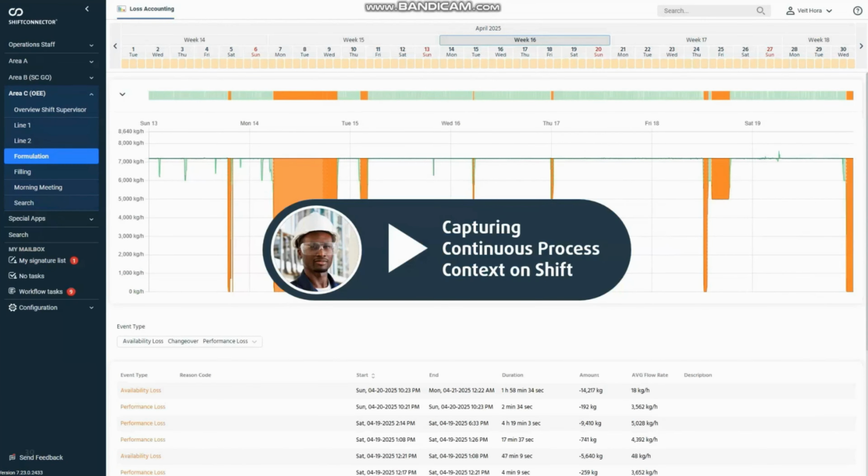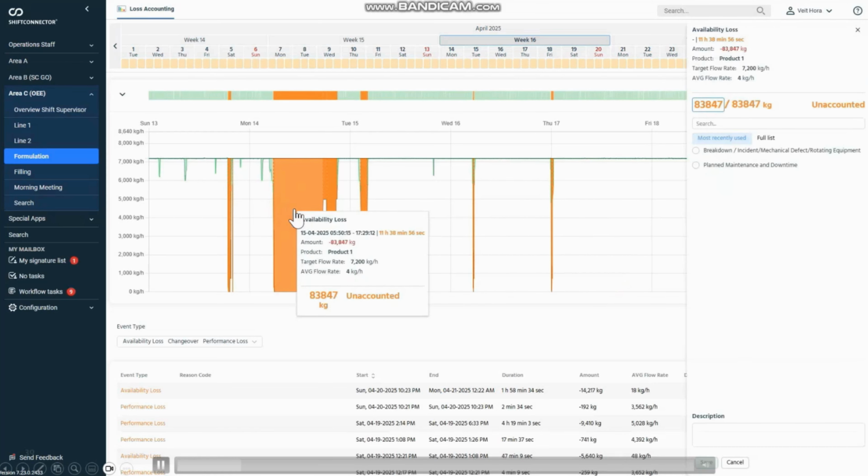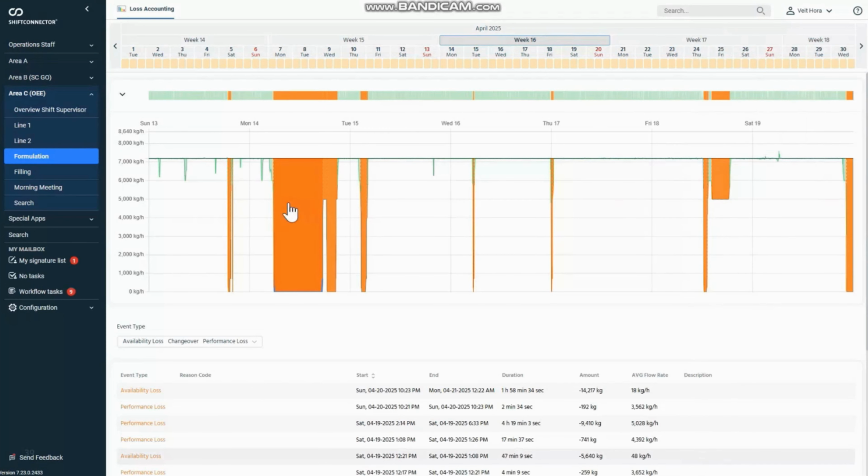So before we get to the checklist, one more example, because we were talking a lot about batch processes. We also want to dive into a continuous example here. So this is where we are looking at a flow rate, which is coming from, in that case, the Aviva PI system, which drops to 0. So we have a downtime, and that's my trigger point to also record a loss on that process. And in this example, we are saying maybe it's an issue with the pump, which stopped because we had product buildup at the sensor, and maybe it just needs regular checking with the inspection rounds and regular cleaning, right?